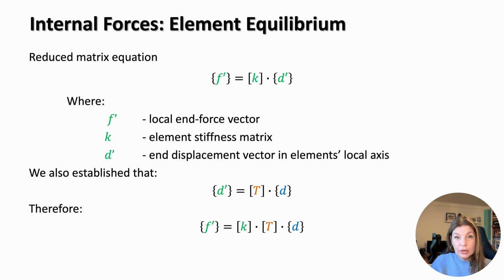It's very important to stress here that the results from this are the end forces. So that will mean the end axial, shear, and moment of the element. So if we have a UDL, it will not give us the moments or forces in the element, only the forces and moments at the ends of the element.